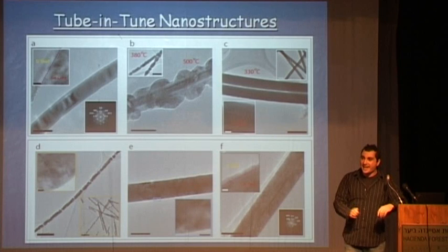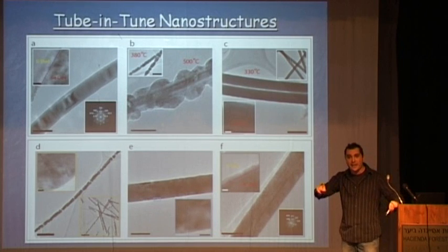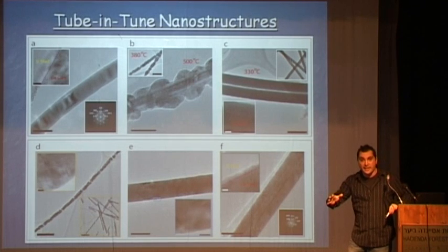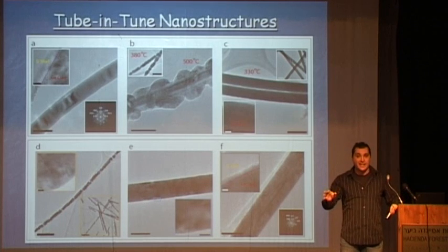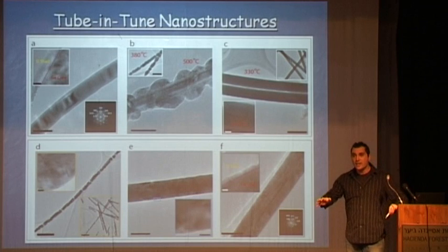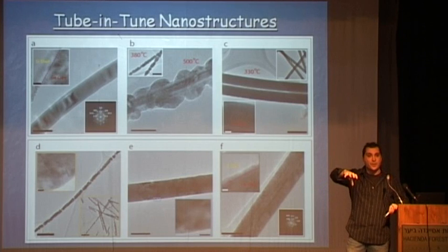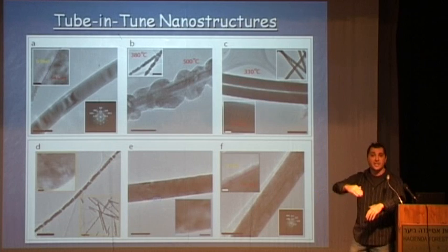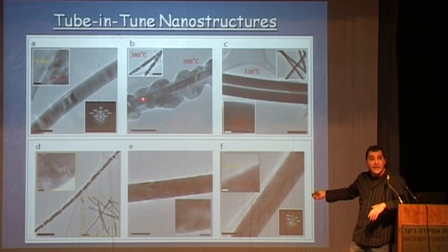It was very, very difficult. Although silicon and germanium have very similar lattice parameters, they still have a very different thermal expansion coefficient. So when you are talking about nanoscale materials, the deposition of silicon and germanium goes through a mechanism called Stranski-Krastanov. It doesn't go directly as a layer-by-layer deposition mechanism, but it goes through island growth because of the stress that is formed on the germanium layer. So we had to find ways to overcome this limiting mechanism.